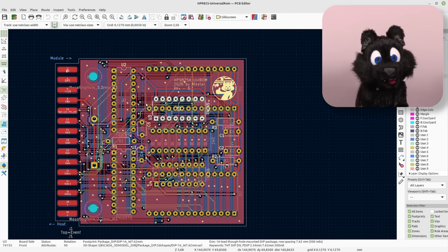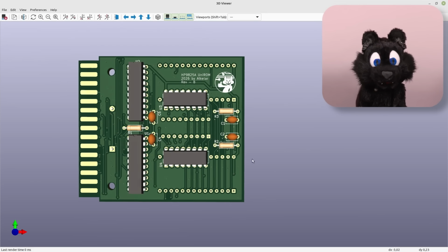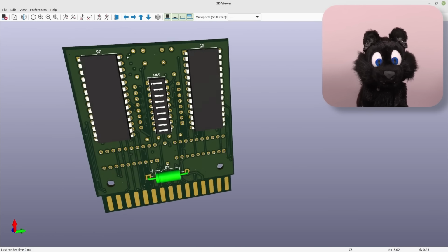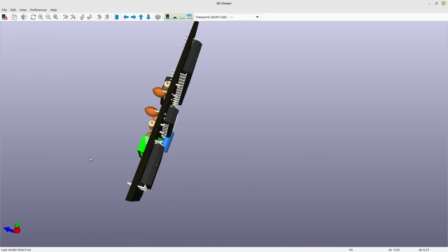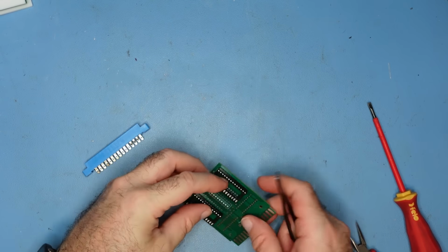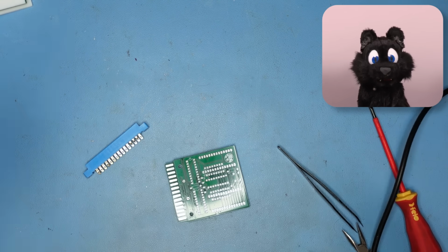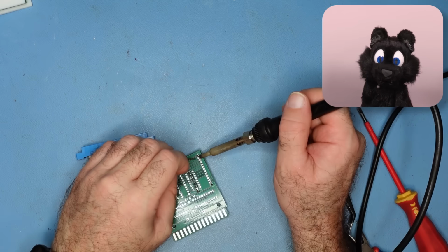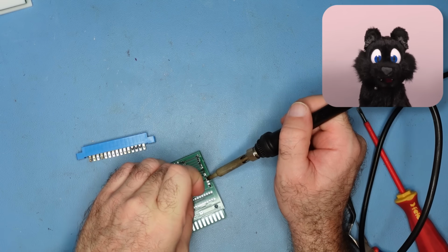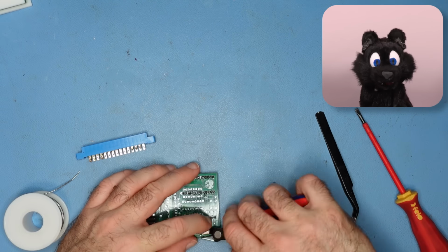I had to discover the change side option in KiCAD to go double-sided with the chips, and also make this my first 4-layer PCB to get everything into that small space. The soldering is a carefully planned sequence since some parts will obscure other solder pads. Oh, and the pins need to be clipped tightly. This stack-up is designed to the fraction of a millimeter.